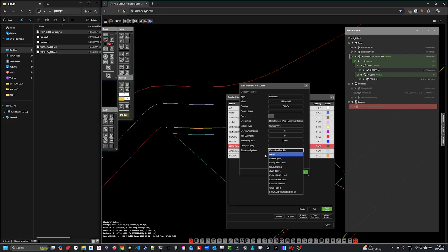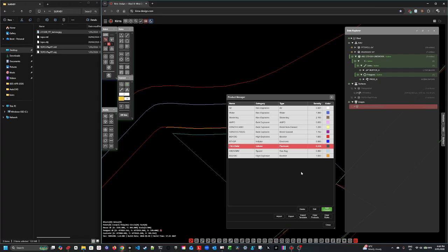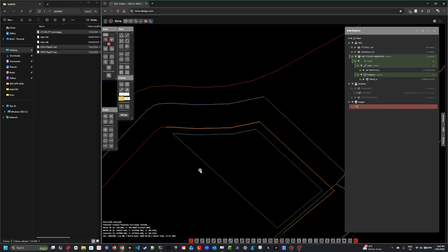Yeah, but anyway, you need to assign your surface wire with your explosive, your detonator type. That's what drives the formatting of the detonator. It's the harness wire in this case. It was just easier to do it that way. Okay, so our harness wire is that, and we're all good. So we've set up our products. We've got our patterns. Let's make some blast holes.